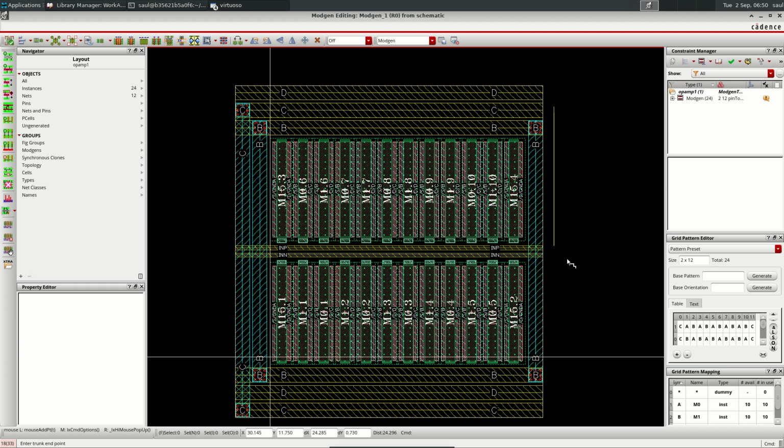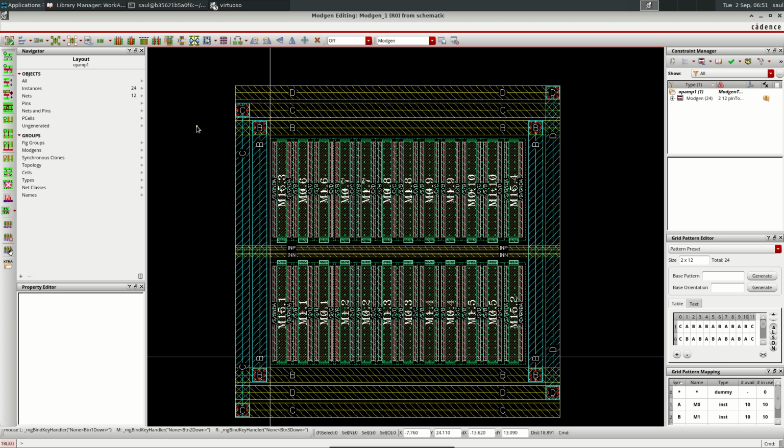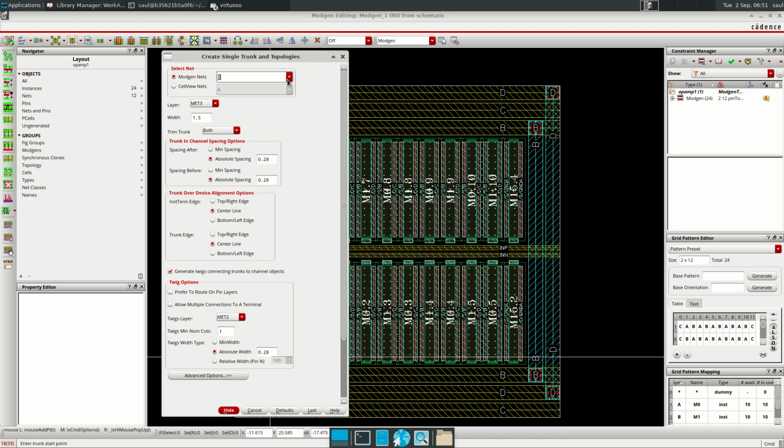We can do the D here and also one D here. So in principle, this should be already over here. D and C are already connected, but if you want, you can connect in both sides to reduce the resistance if you need, at the expense of a little bit more parasitic. So I'm going to do that because we are not constrained by space right now.